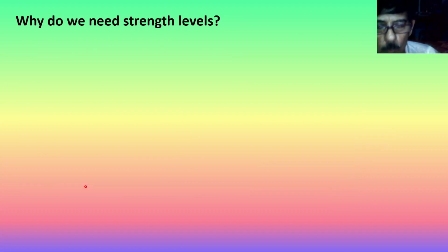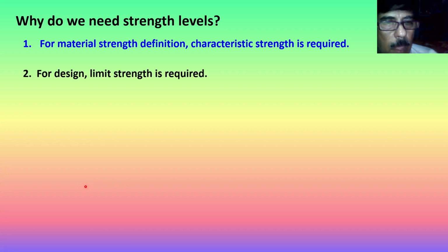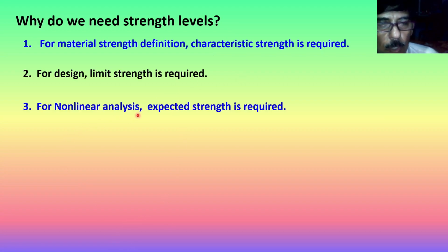Now the question is, why do we require the strength levels? Let us see. For material strength definition, we require the characteristic strength of the material. For design purpose, we require limit strength. For nonlinear analysis, expected strength is required.